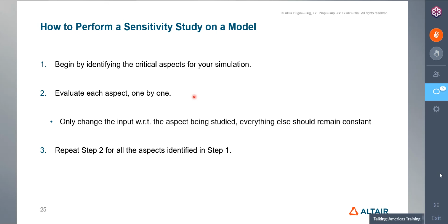Because like I mentioned before, the finer that mesh is, the smaller those elements are, the more accurate it is. Now, there's a certain point where your solution's not really affected by the size anymore, because your element size is small enough to capture whatever's going on in that area accurately. So making it smaller would probably not make a difference. However, on the other side of that, if your mesh is too coarse, your element sizes are too big, your solution might be erratic, or it could behave very weird, and might not make much sense.